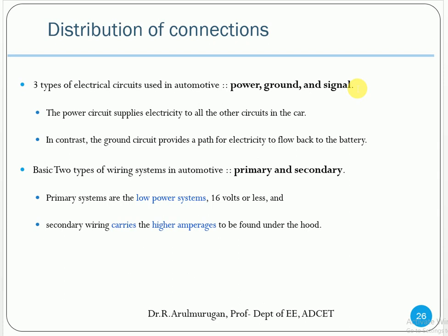If you look at the electrical vehicle accelerator, it consists of 3 wires from the battery, from the controller. I will repeat. Okay, the electrical vehicle accelerator, a 3 wire system from the controller. One is a plus, one is a minus, another one is the signal. About the signal, the wire will come.